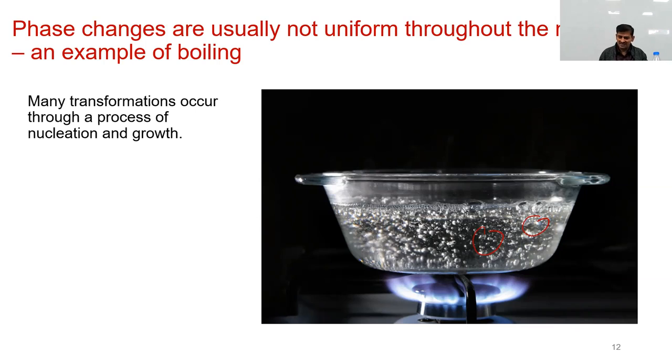So the point here is this kind of simple analogy applies to many processes of nucleation and growth, where the second phase, in this case it was vapor, we can have solid from liquid, or if we are talking of two solid phases transforming into each other, alpha and beta, even then beta phase would first nucleate inside that alpha. It would form small regions, and then those regions would grow. So that is what nucleation and growth is roughly all about.